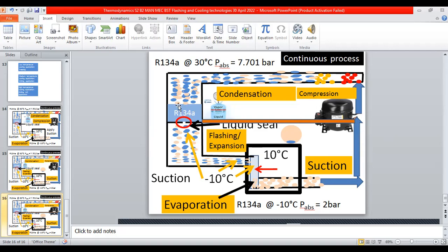So the compressor and the flow restrictor, flow control or expansion device, are the two elements responsible for this high and low pressure, and to utilize this flashing effect. So you can see vapor compressed, condense, flashing, suction again, and evaporates and turns into fully gas and back to compression. So we call this vapor compression cooling system. Okay, vapor compression refrigeration or cooling applications.